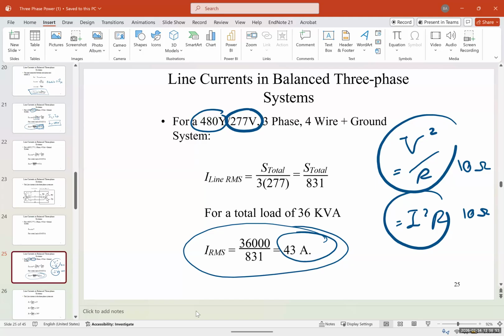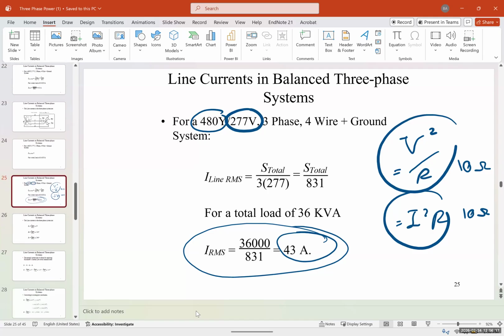It's a very thick wire. It's going to be dangerous. So those things, we usually have higher voltage and we reduce current. Is it clear? Okay. So now 43, and I will explain if you want, I can write the equation, it's out of the scope of this class. You can see that you actually reduce the thickness of the wire by almost 1/4. And you're going to save a huge amount of money.